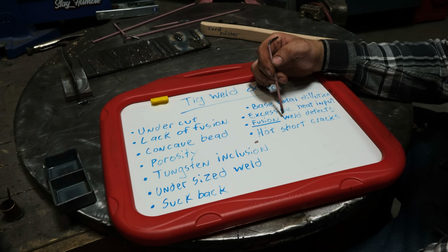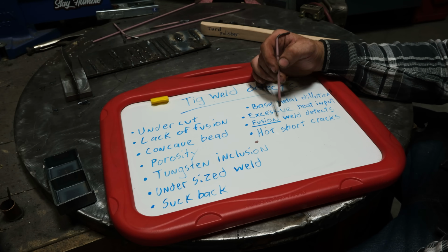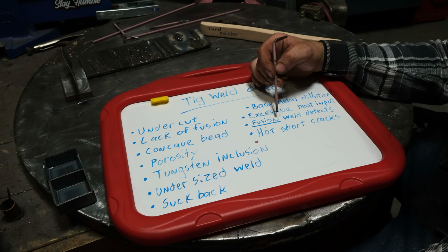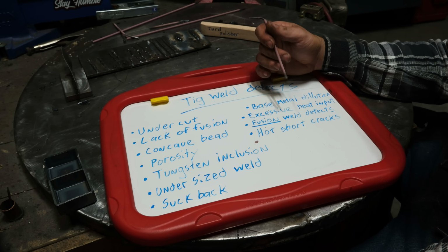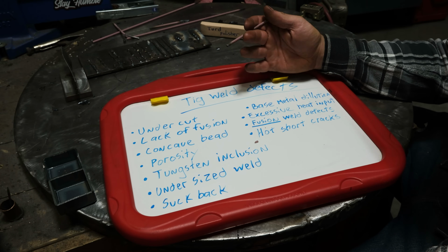Now, going back to fusion welding, where you're not using any filler, you're just fusing the material with the material itself, that is very common on things like thin stainless. Like, I'm certified to TIG weld basically unlimited fusion weld for pipe, okay?